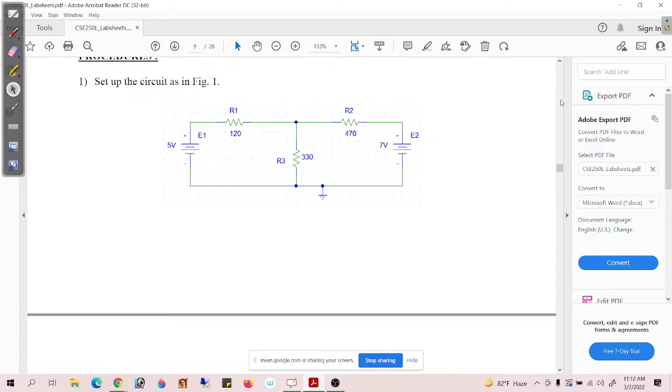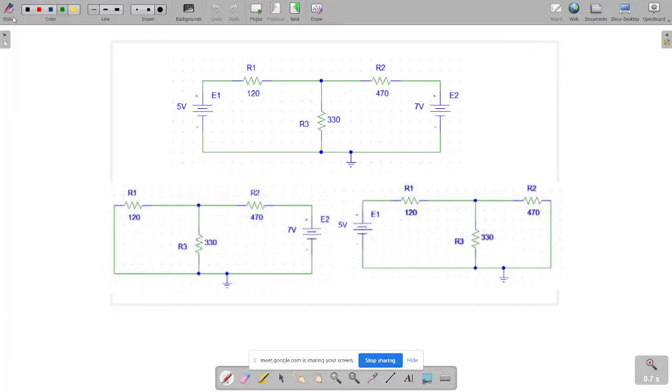So what superposition basically means is that this principle, this theorem, is only applicable for linear circuits. Do we all know what linear circuit means? If not, let me tell you, linear circuits are basically circuits composed of nothing but simple linear elements such as resistors, voltage sources, or current sources. These are linear elements or components. So for linear circuits, the superposition theorem is applicable.